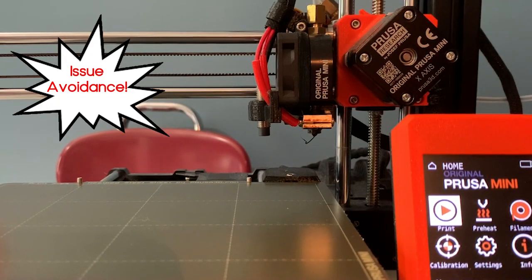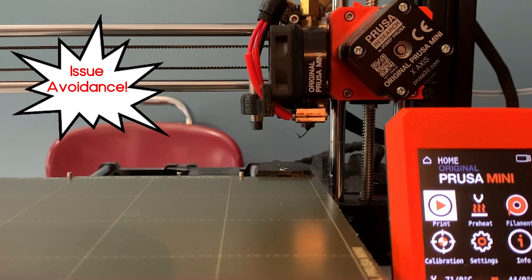Before we move on, I wanted to quickly go over a potential issue which might occur especially when first using the printer. If the nozzle height above the heat bed is too low, the print will look streaky. If it's too high, the filament might not stick to the bed. Ours sits at around -1.3 millimeters. I recommend using the first level calibration test to adjust the nozzle and find the correct height.